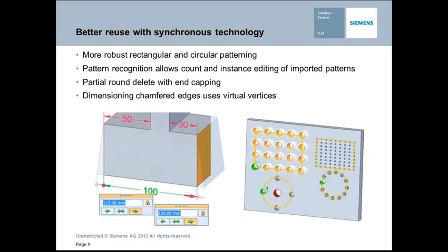So with that said, if you didn't know that we can recognize holes from an import of a dumb solid, we can, and we can recognize things like counterbores, countersinks, shouldn't say threads. I don't think we've got them there yet, but we can recognize the holes as being holes on the import of a dumb part. But now in ST6, we go one further. We can now recognize patterns. So that's very exciting. I use it all the time now.